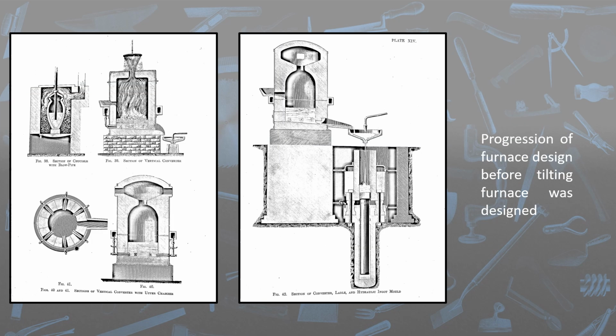To contain the material resulting from the violent eruption from the top of the furnace, which was known as the blow, Bessemer designed another vertical cylindrical vessel, but this time with an upper chamber. As before, the converter had 6 tuyeres placed around the lower part of the converter to blow air into the molten pig iron. When the reaction was complete, the malleable iron was poured into hydraulically operated ingot moulds.